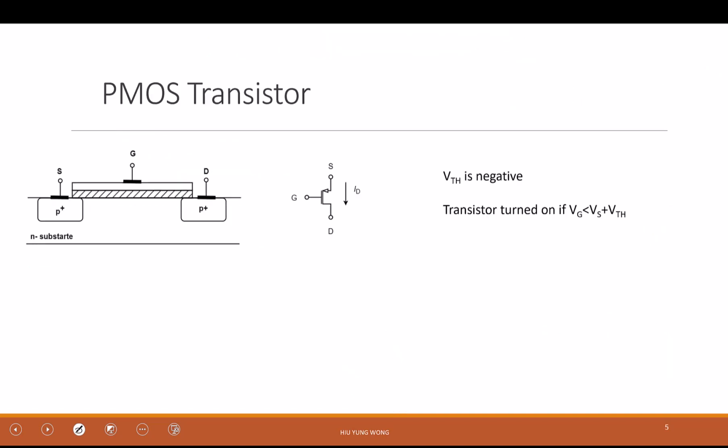But we can look at PMOS again, and that can help us to review, right? So what is PMOS? It's P-type. Everything is the same as NMOS, except that this time we have a lot of holes in the source and drain, and in the substrate we have electrons because it is N-type. Everything is just opposite. Change the polarity. So let's look at the scenario. For example, this is P plus, this is P plus, and this is N.